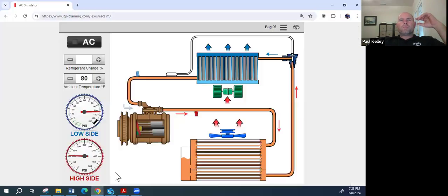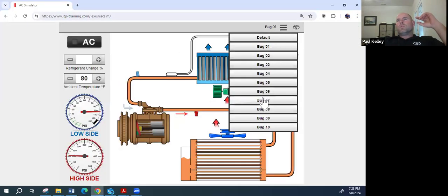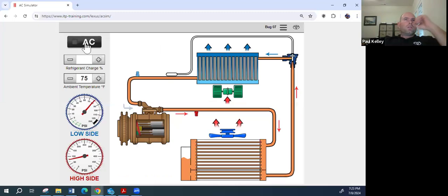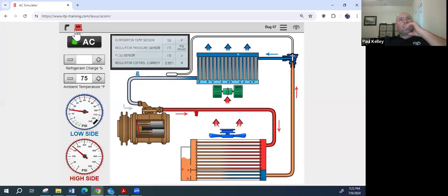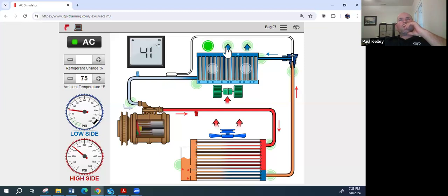So we go to the car. Number 7. Turn the AC on. Temp gun. It's 41, 41. Shoot, this thing's freezing. Don't you think? What was the concern again? Remind me. Oh, it doesn't cool at times. So you might have to put a little bit more time in this one, right? If it's an intermittent issue, you might have to babysit it, drive it, mess around with it, you might say, hey, when is it not cool? What do you have to do?